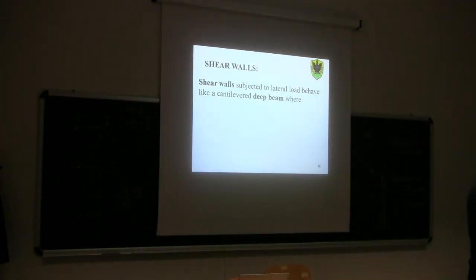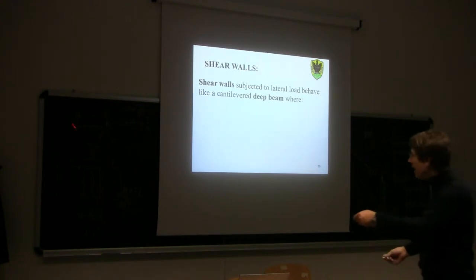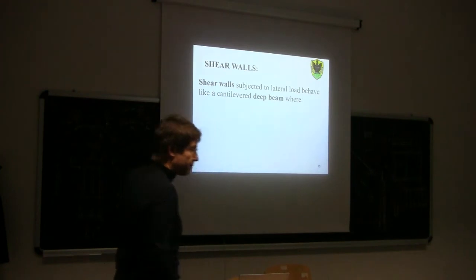Because we have so many approximations before and after that having an approximation here like this is not going to change too much. Also because you see, in reality, our cross-section here, we said it's not glued. So we don't have a cross-section which has this shape. We have here a mechanical connection. So the formulas of mechanics of materials wouldn't be rigorous in our case because we have a nail connection which is flexible. Okay? So for us, it's more than enough to find a solution like this.